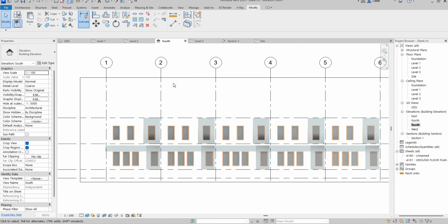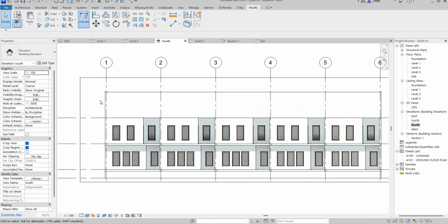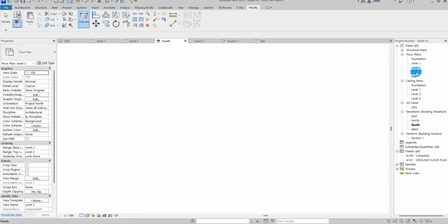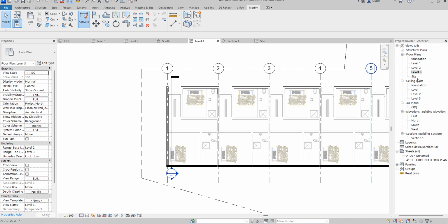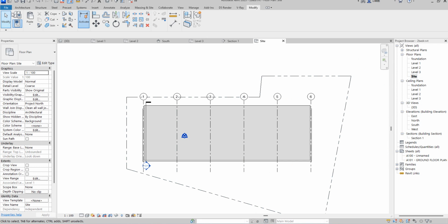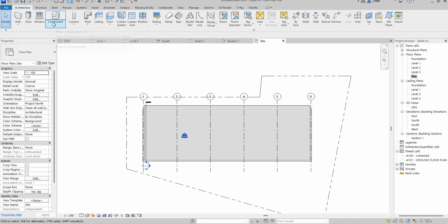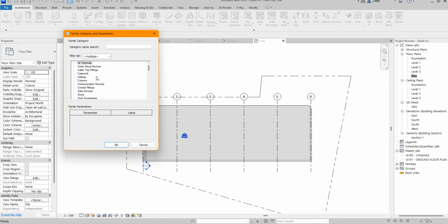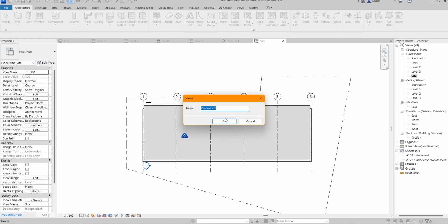So if you are the type that shies away from how to do that, all you just need to do is concentrate on creating lines. So let us start one after the other. The first thing you need to do is go to the coping of the roof. I'm going to go to sites this time around. So say components, I will say model in place. So I'm going to select and I'll say placement 1.